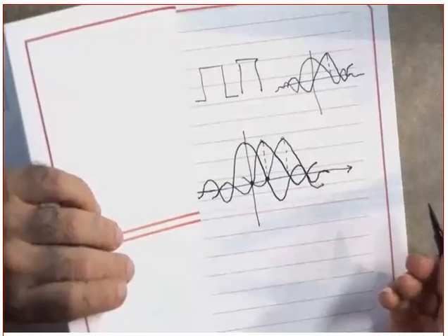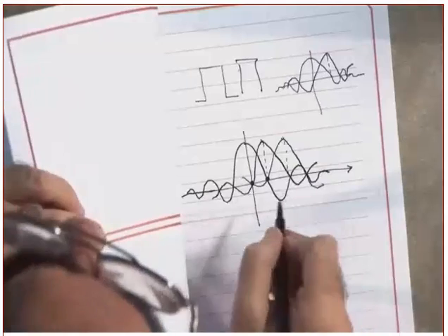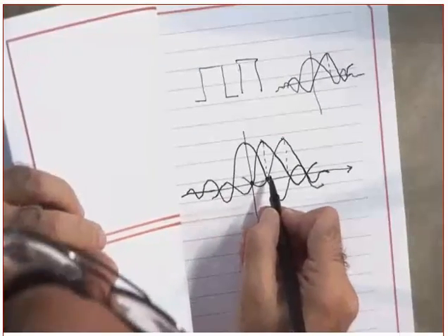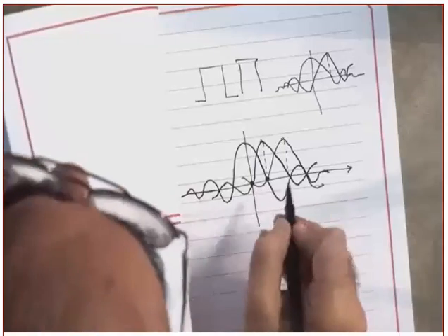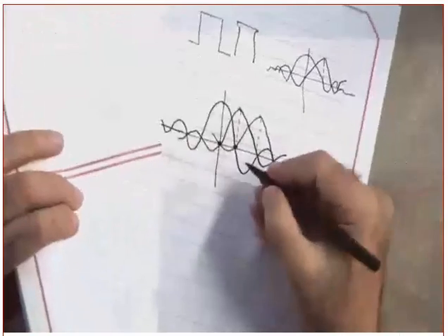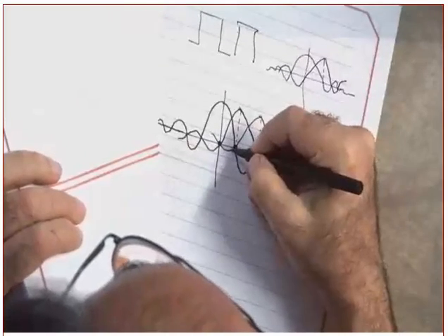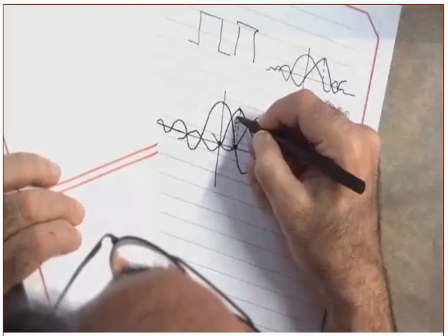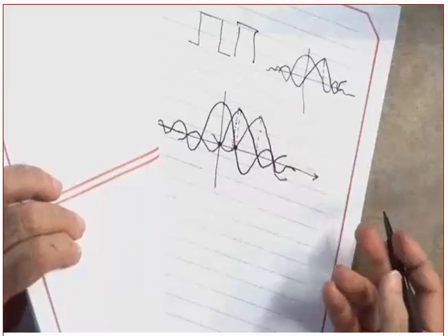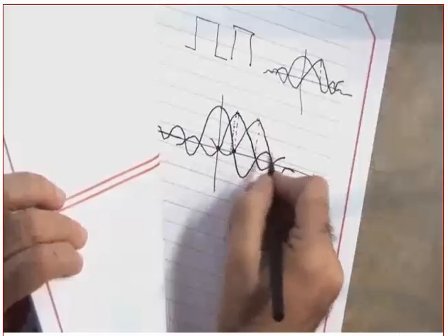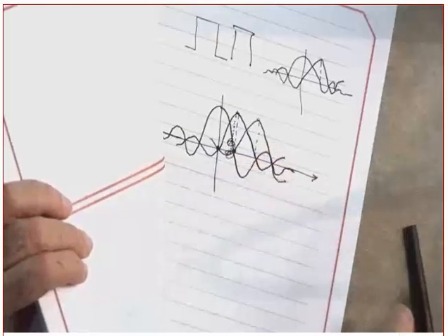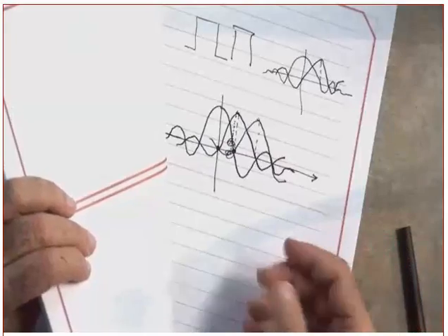The next one is this. Are you following me or not? Okay, but the problem, this one here, it means at the receiver, you need to have a precise timing. If there is a small jitter, what will happen? Tell me what will happen. Let's assume that you sample it in here. Will you have intersymbol interference? You will have intersymbol interference if there is a jitter in timing. The effect of the adjacent samples will be very heavy. Did you get my point or not?